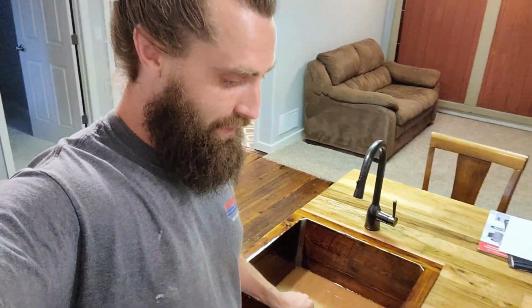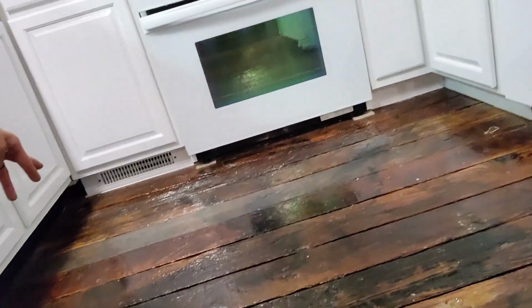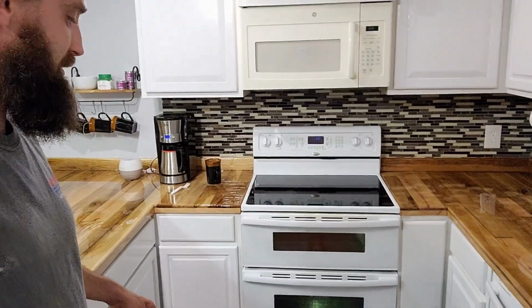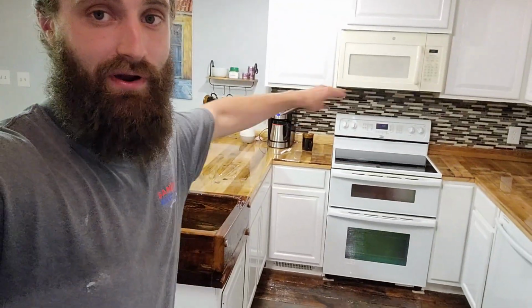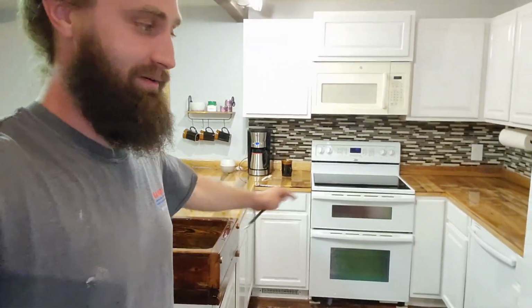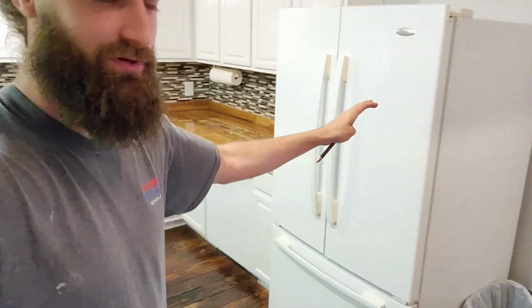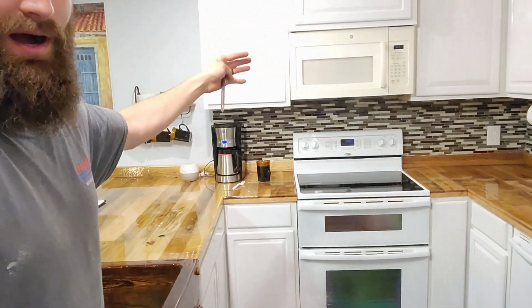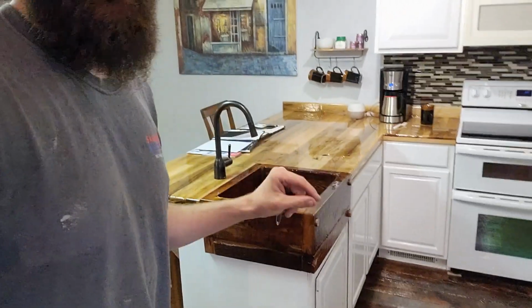So we've got a high latent load. We've got a high load from all the people in the room. We've got nice big ovens. We've got cooktops. We've got microwaves. We've got these big double reach-in freezers and refrigerators that off the back side of them have these condenser coils that are just dumping heat into the area. There's a lot of heat that is generated in a kitchen, and there's also a lot of lights. So that's something else we've got to look at. How many lights are in these kitchens? They all are burning heat. So as we move through here, we're going to take a look.